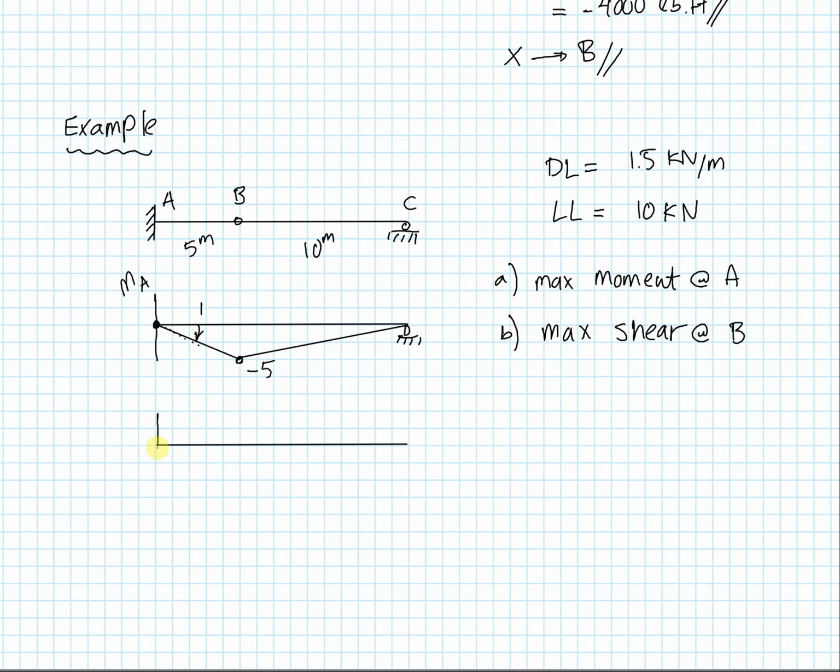Now we're going to do the same thing for VB, and we know that there's a roller at C, and so this time, this is where our hinge is. This time the left span is not going to move, again, because it's fixed at this position. And when we introduce the slider, the right side of the hinge is going to go up by a magnitude of 1 per the principle, and it's going to go back down.